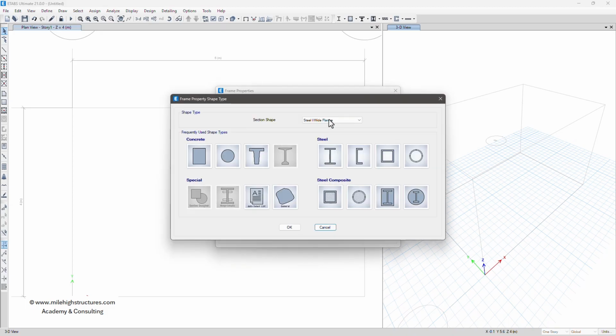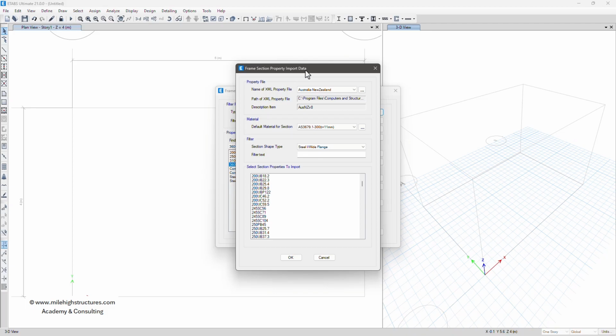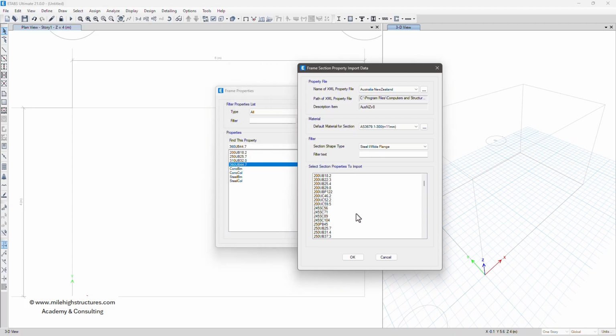One of the mistakes that a new engineer usually makes is this. Let us say we have this 250 and 310. Considering 250, we have 25.7 kg per running meter, but we also have 250 UB 31.4 or 37.3 kg per running meter. If we are going to select 37.3 kg per running meter, it is better to opt for 310, which has 32 kg per running meter, because we shall have much more sectional modulus and second moment of area in this case. That is the thing that you need to understand.